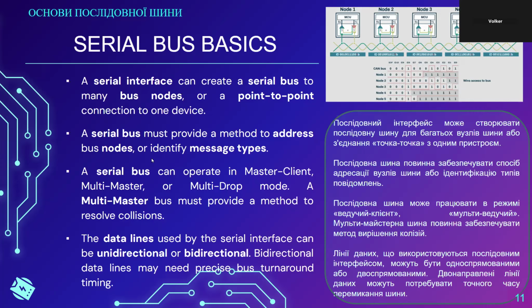But for systems like the SPI bus and the I2C bus, generally the microcontroller is the master. A number of peripheral devices are the clients. Could be just one device, it can be several. But the master device is asking for information or issuing commands to the client device and getting responses back.